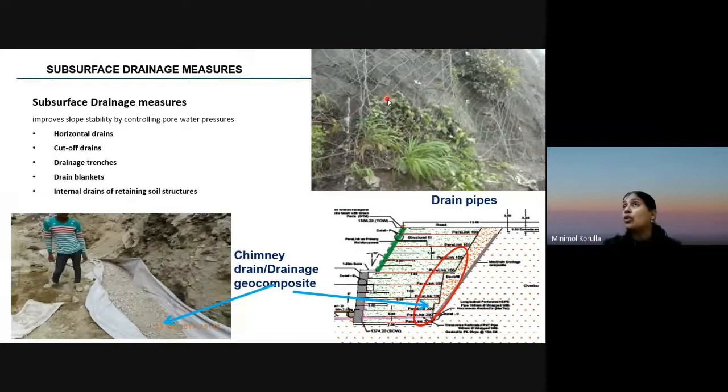There a lot of rock falls and slides were happening, and it was found that the seeping water, or the subsurface water, is the problem. In appropriate places, with the help of a geologist, horizontal pipes are inserted, and through this pipe the subsurface flows are happening.